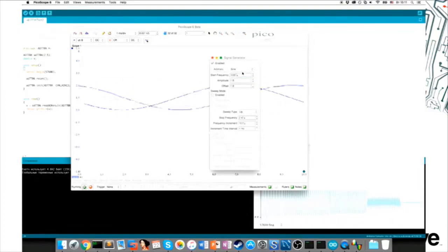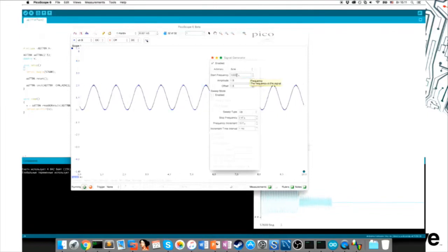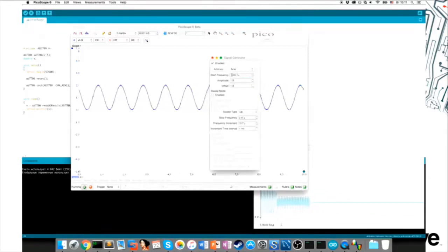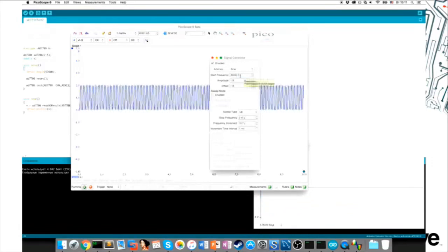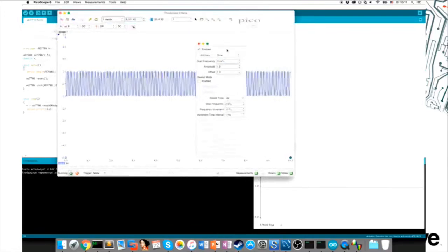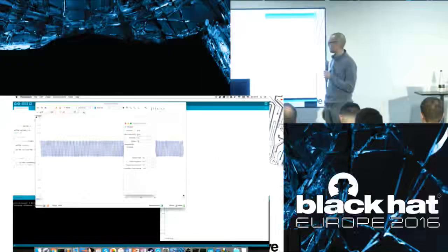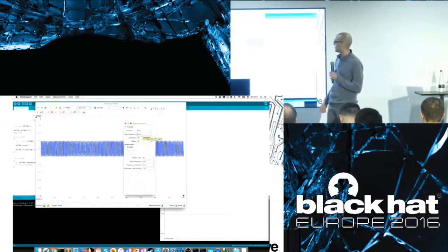So we're getting the signal here, and once we get out of the filter, we start getting an attenuated signal. We're already out of the frequencies that are supposed to be sampled by the ADC. So this is okay. We are not having any aliasing problem, we are just getting noise. As we can see, we started increasing the frequencies, and I'm going to give a bit of a spoiler: the frequency is 31250. These are frequencies that should be completely blocked by the system.